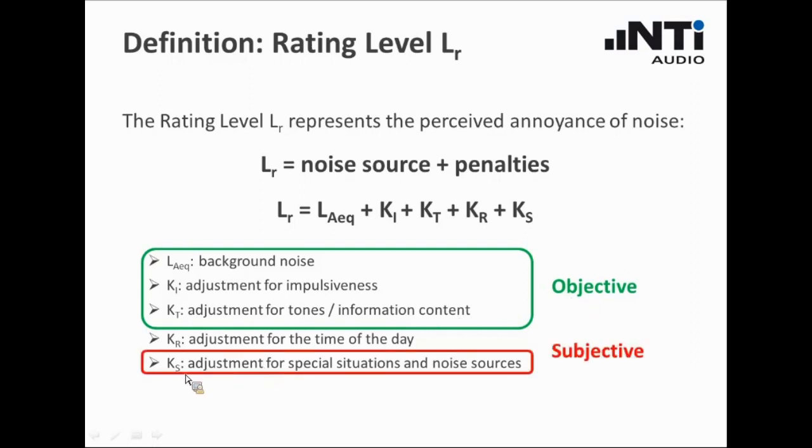On the other side, this special adjustment is reserved for a subjective assessment, and that is very important: the standards include the statement that you, as the acoustic expert, have to subjectively assess whether additional penalties have to be applied because there are some specifically annoying sound components that cannot be detected with these objective measurements.